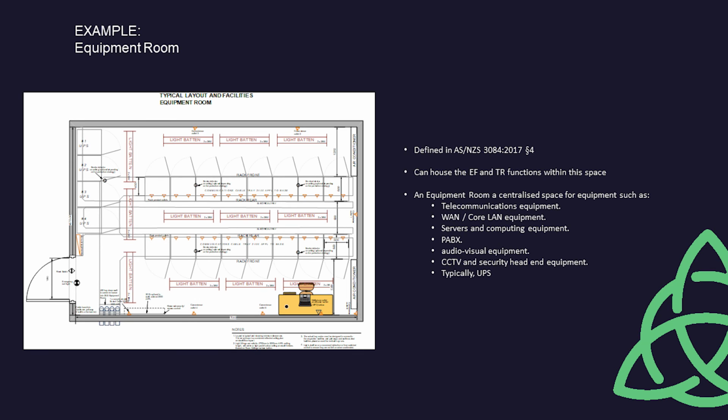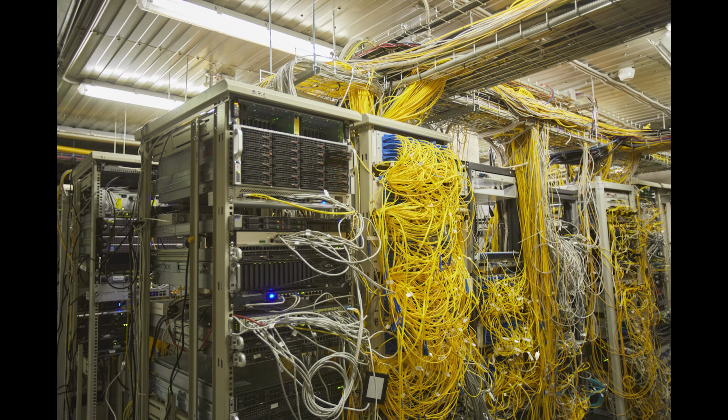Additionally, the fixed ceilings or suspended slabs above, acting as a ceiling, must be painted in ceiling matte white. The wall and ceiling matte color must be consistent with other finishes within the room. The paint also has the benefit of sealing the ceiling and walls. This must be completed before mounting frames, equipment, and surface fittings are installed so that unpainted surfaces will not be exposed if equipment or fixtures are changed or moved in the future. If the equipment room is an external, standalone structure, any walls and ceiling on the outside of the buildings must be fully insulated to minimize the solar heat load during warm weather.